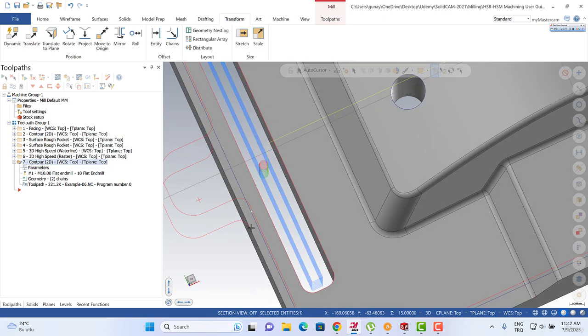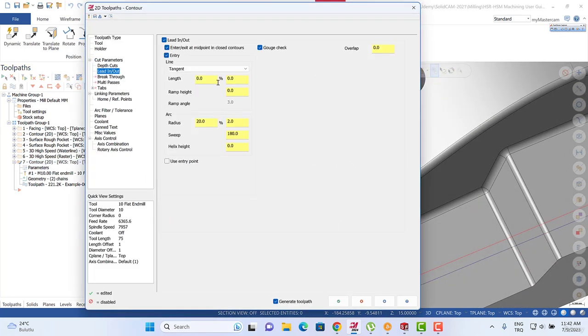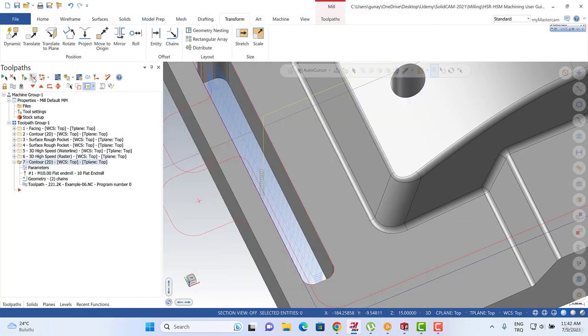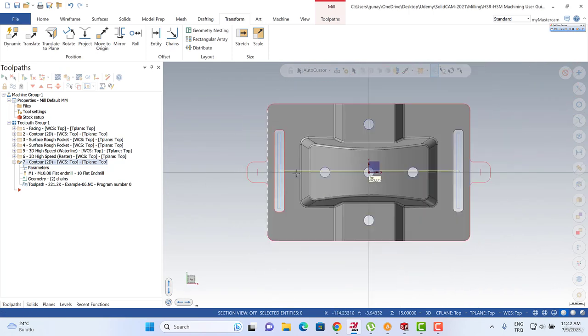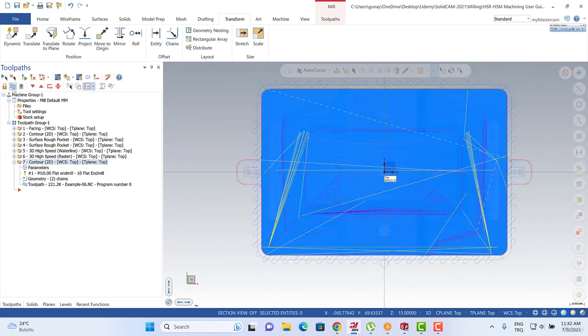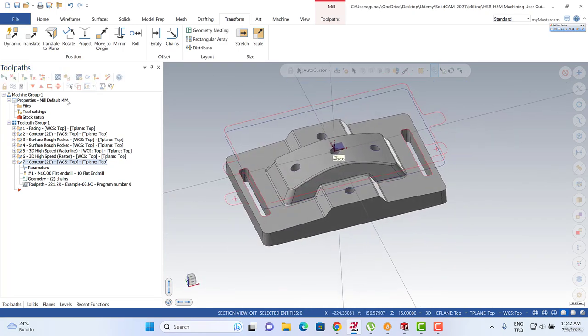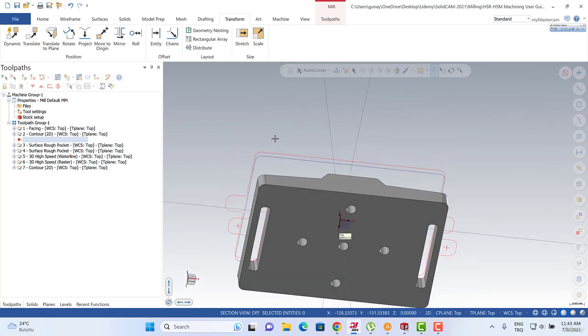Okay, maybe we should change our lead in and lead out process. It can be 10% of my tool diameter, and it is calculated right now, as you can see. Okay, so that's fine. This is the final operations, and after that maybe we should also turn to here. After the face and contour toolpath, we can turn to the 2D and with the position of the 0, and then we can turn to here to create our drilling process.